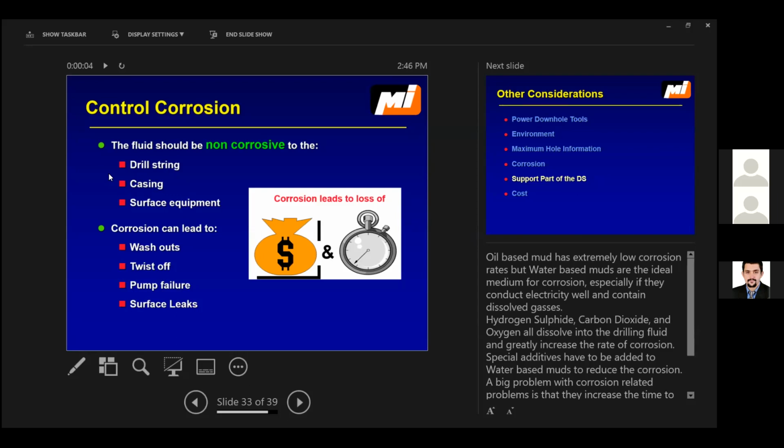You know, all of the drilling equipment are metal, so they are exposed to corrosion in any piece of the equipment, which may cause washouts. Washouts means something like pitting, and when pitting increases, it causes holes in the metal. It may cause loss in the drilling flows, loss in pressure, and too many problems in the well.